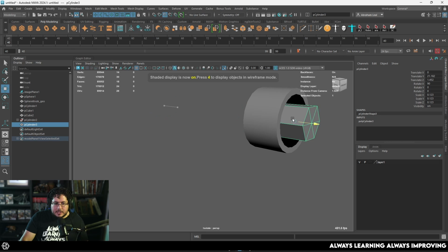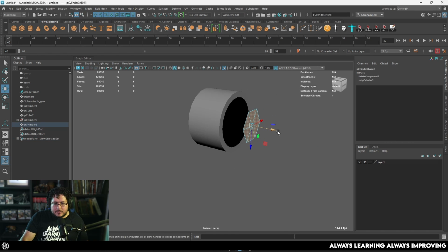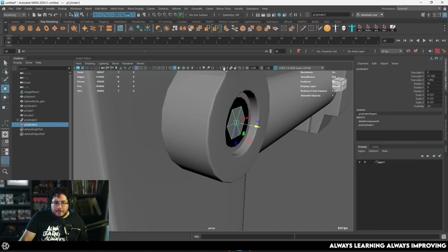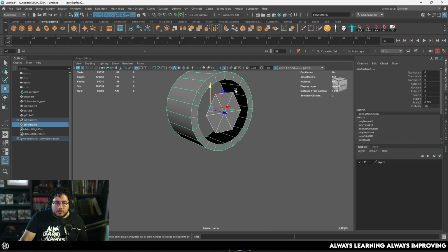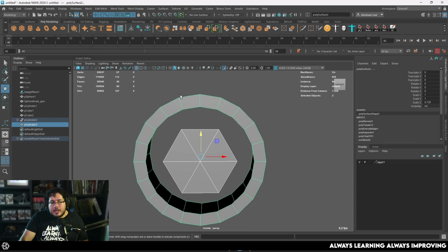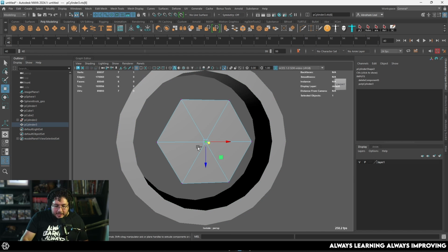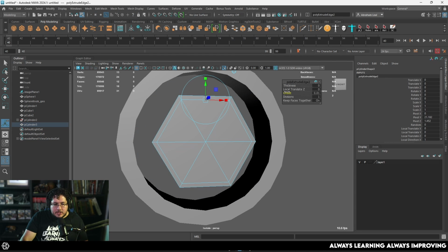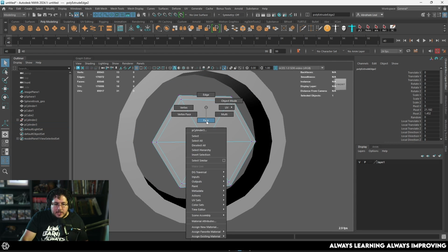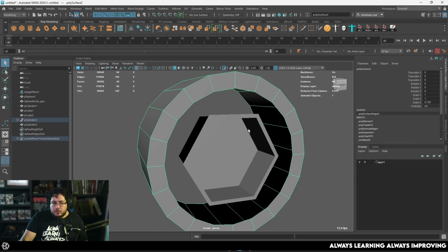This is a very nice topology lesson, because we are going to start with this face right here, and we want to combine it so that we go all the way to 20. Why do we want to do this? Well, what's the purpose of this? The main purpose is that we want to have a very smooth round border, but we want to keep this very nice tight effect right here. So I know that for this one right here, I'm going to create a little bit of a loop. So I'm going to offset this just a little bit, just around there, because eventually all of these faces are going to be extruded in, right? To create a little hole for the bolt.